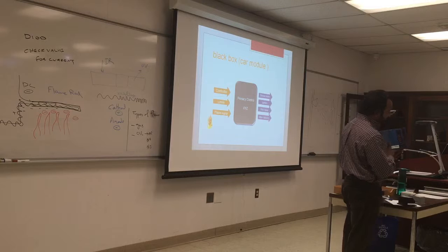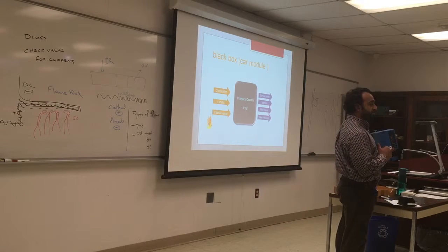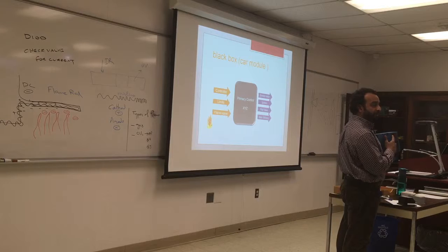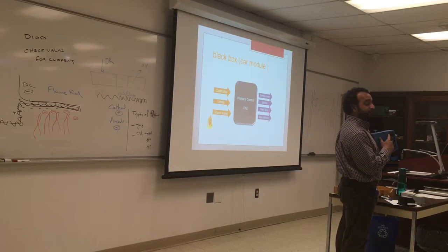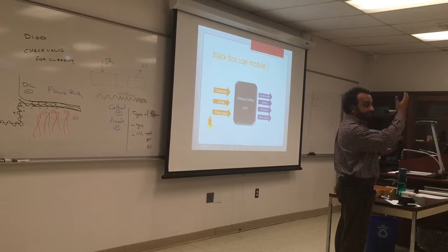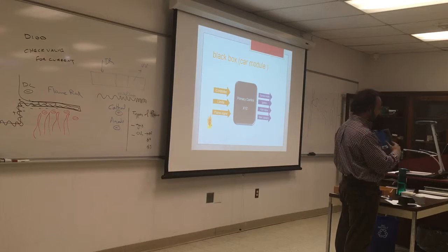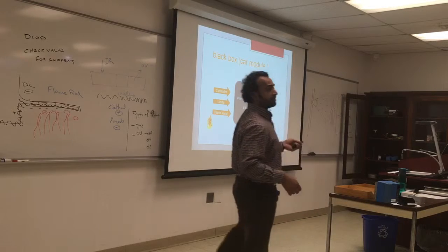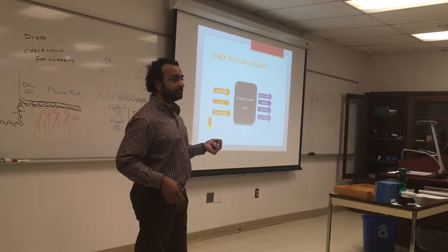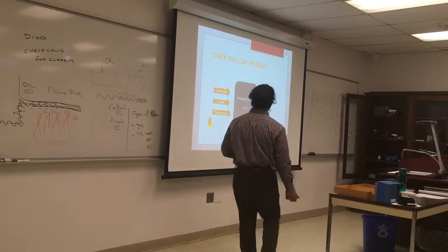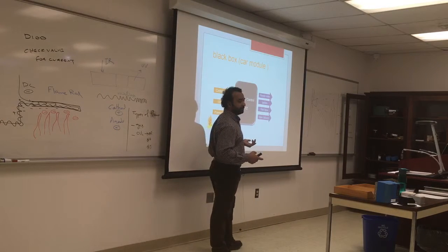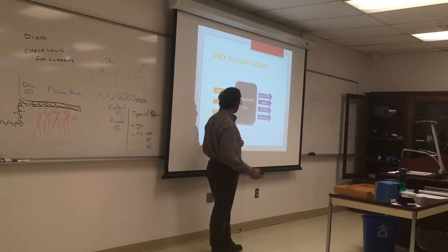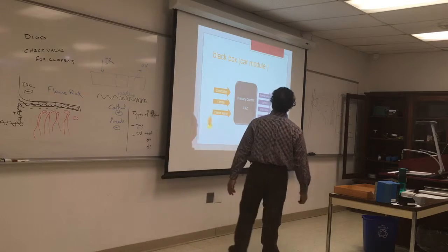If you look at this control, this is one of the recent ones. It's still in the field. It has an error code here, like a car computer. It gave you A26, A2, and there's a list of them. The manual tells you what the issue is. And you have some LEDs here that tell you what state it is in. We will try to wire some of these and see them work. But again, we do not investigate what's in the control. Same with the new ones for the primary. We check the limits, we check the inputs, and we check the outputs.